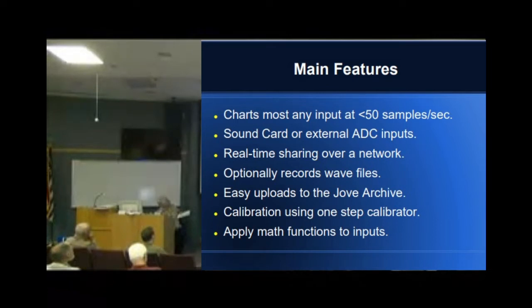You can use a sound card to get your data into radio SkyPipe from the receiver. Or you could use an ADC input, analog to digital converter input, and we used to do that pretty often. We detect the sound outside of the computer and then produce a DC voltage and then measure that. But the sound card accomplishes pretty much the same thing.